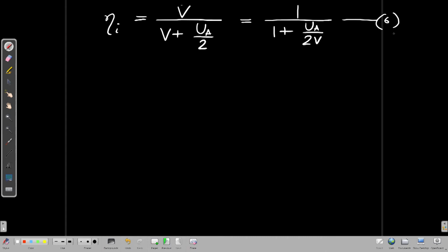So, this is the same equation that we have obtained as before. Now, for a ducted propeller, we have the propeller thrust, which is Tp, and the total thrust To from the duct and propeller combined, and we will define a factor tau, which is the ratio of the thrust generated by the propeller to the total thrust from the ducted propeller system.